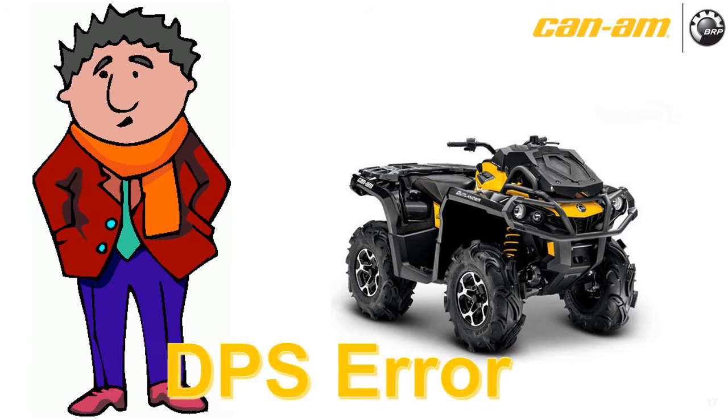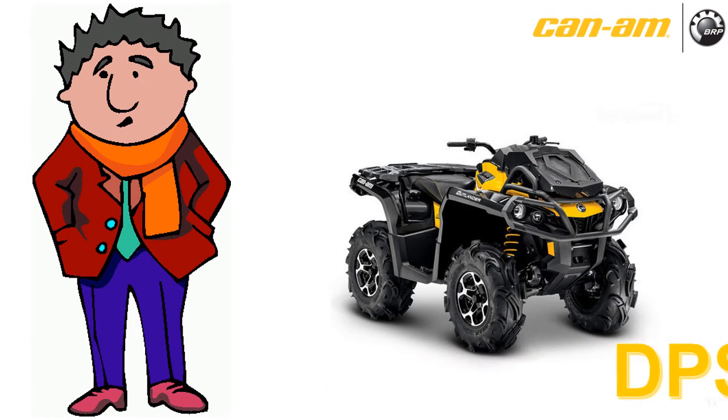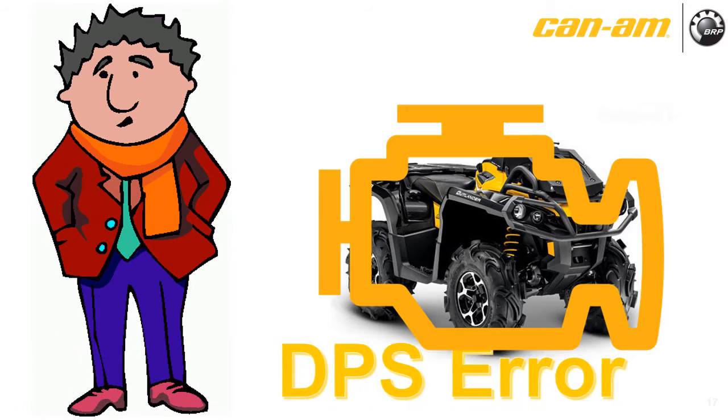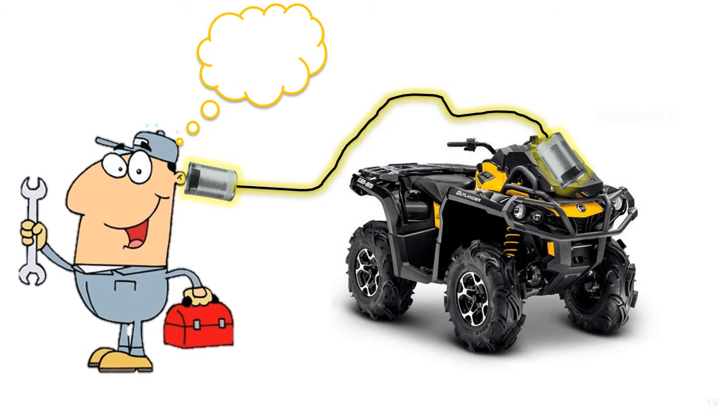Here's a real-life example on a 2014 Outlander XMR. The owner complained of a scrolling DPS error message and a check engine light. The technician described the symptoms as, "We cannot communicate with the unit using BUDS. The ATV will start and run, there's no gear position indicated, the DPS is inoperable, but other than that, it runs fine." There might be a communication problem with the vehicle.